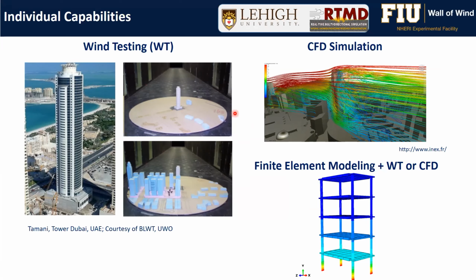I must say for wind tunnel testing, the limitations are basically about the scaling, because when we scale down a larger scale structure, a big structure like this, to a smaller scale model, we are missing some of the real wind impacts on the structure. And it would mainly affect the peak forces or the peak pressures acting on the structure. Once you scale it down to a typical length scale in a wind tunnel, it could be 1 to 400, for example. So it's as small as that.